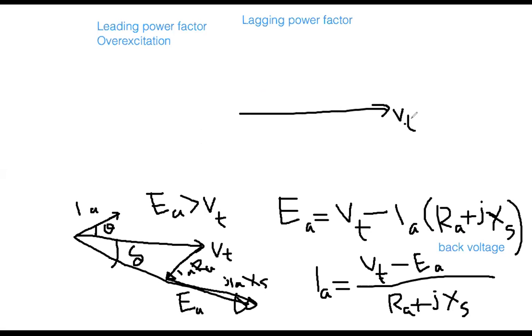And then because it is unity power factor case, definitely IA will be on the same line. There is no phase difference, theta is 0. And now everybody look, again, if it would be plus sign, then I would go in this direction to represent IA RA. But instead of going that side, it will be in this direction. For example, this is your magnitude of IA RA. For example, this portion.